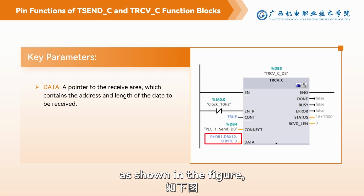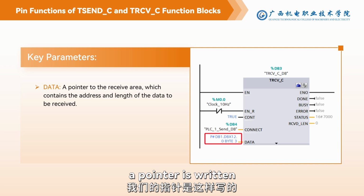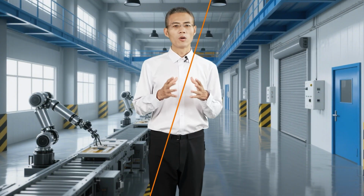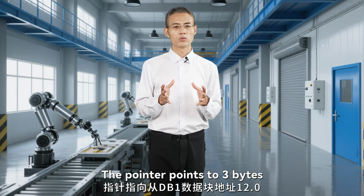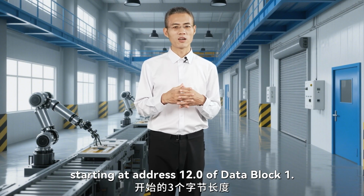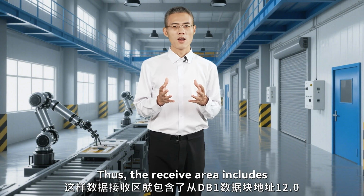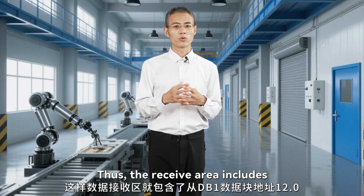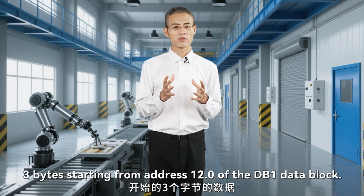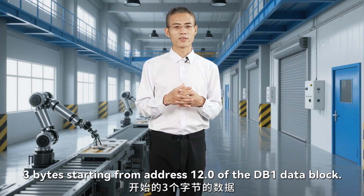Specifically, as shown in the figure, a pointer is written as P#DB1.DBX12.0 BYTE 3, which means the pointer points to 3 bytes starting at address 12.0 of data block 1. Thus, the receive area includes 3 bytes starting from address 12.0 of the DB1 data block.